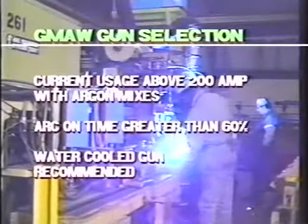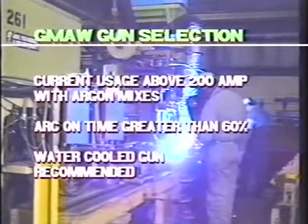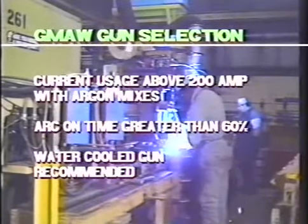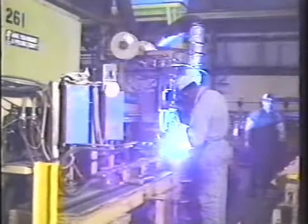When welding with argon mixes above 200 amps at an arc-on time over 60%, a water-cooled gun is recommended. When using argon mixes above 200 amps and an arc-on time over 50%, to extend the nozzle life, use a heavy-duty gas nozzle.